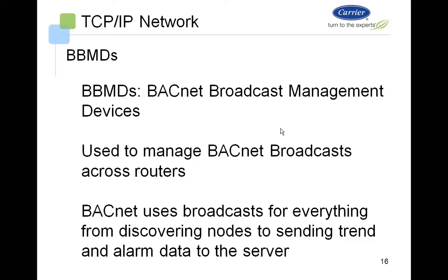And when you have IP networks, you typically will have devices that are sitting under different routers on the networks. And the routers themselves, they don't pass general broadcasts through them. So BACnet had to come up with a way of managing the broadcasts to get them across routers, and this is done using the BBMDs.